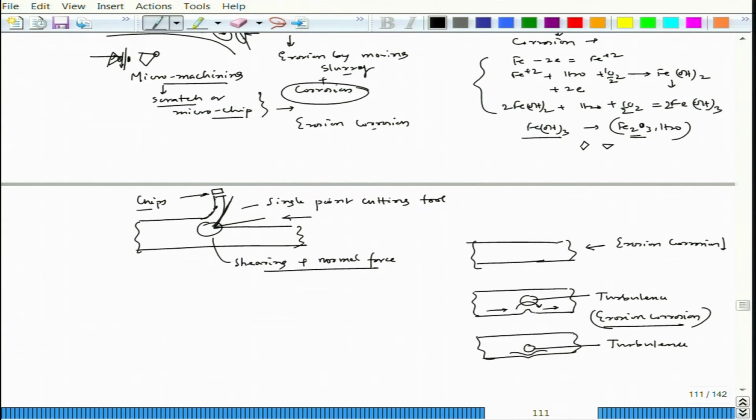In fact, when you have this kind of inner pipe situation, that might lead to a greater problem, because you know your wall could be like this. Okay. Now, in this case leakage problem would be less, because this part would get chipped off. But in this case, if this part is gradually moving down and the cross sectional thickness is less here compared to this, so this part might get leaked. So, that kind of situation might arise.